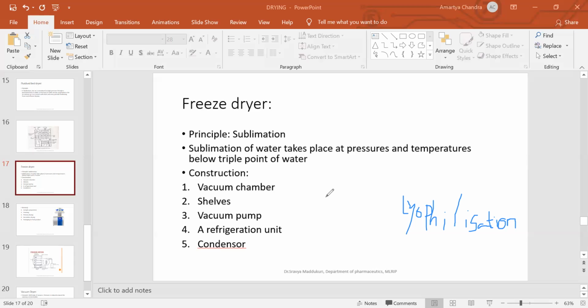It has to become ice and then be subjected under high vacuum to heat by conduction, by radiation, or both. Right? No convection takes place because there's no water involved. By conduction and radiation under high vacuum, the frozen liquid sublimes, leaving only the non-volatile solid. The frozen liquid will undergo sublimation. What is left behind is only the non-volatile solid. Whatever is volatile will undergo sublimation.